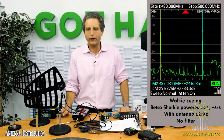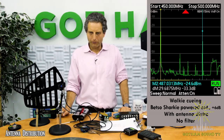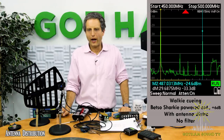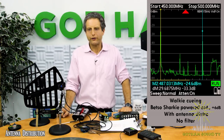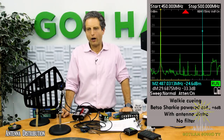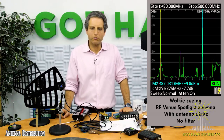Yeah, so this is our Sharky antenna plus 6 dB. We can see on the left that spike is a walkie cueing. That's part of the noise, and you can see the baseline noise floor, I would say averaging minus 74 dBm. And our Electrovoice transmitter on the right, denoted M2 at minus 24.6 dBm, is a very strong signal, significantly above the noise floor. That would make a great reception, but also look at the noise floor. Remember, we're trying to maximize our signal and minimize our noise. So let's see the second slide, Jared, please.